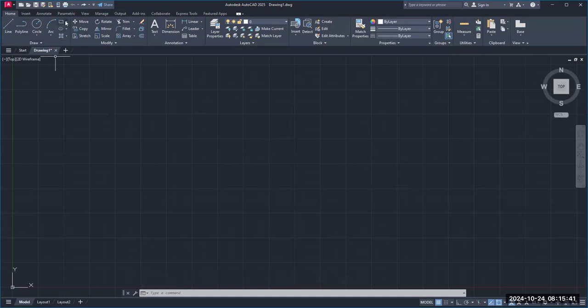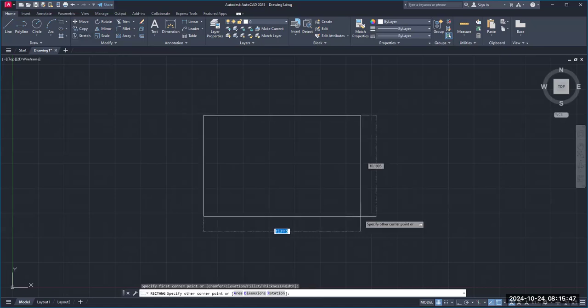So watch, I'm going to select rectangle, 2-point click, and notice I have 2 floating dimensions here, right? The one that's in blue is the one they're asking for input. So I'm going to type in 3.625, and hit the tab key.